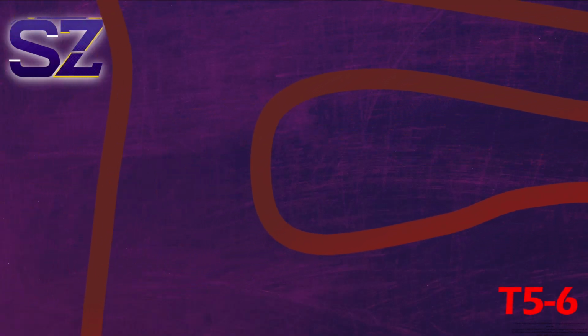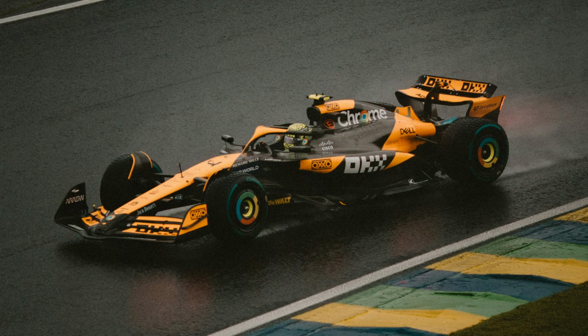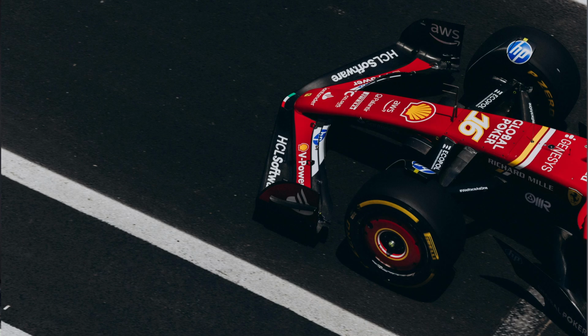In turns 5 through 6, these medium sweepers test lateral stability. Aero balance is king here. Teams may tweak their front wing flap angle and floor edge vortices to tune mid-corner balance. Turns 7 through 9 is all about curb survival. It's where suspension kinematics really matter the most. Teams try to manage grip, whilst adjusting the travel range of the suspension to accommodate for the curbs.